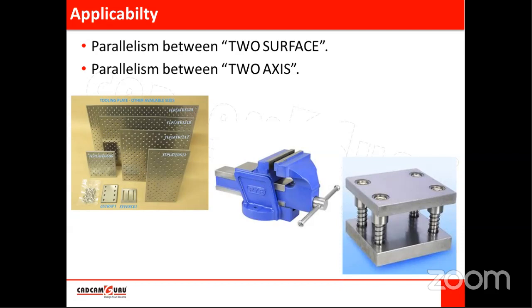It means if the punch and die have an offset, or their axes are not aligned properly, then the shape of the punched hole will have some error. It will not be a pure circle. So to ensure alignment of the punch and die cavity, here there will be a die, and here there will be a punch mounted on this upper plate. Alignment of punch and die is very important.